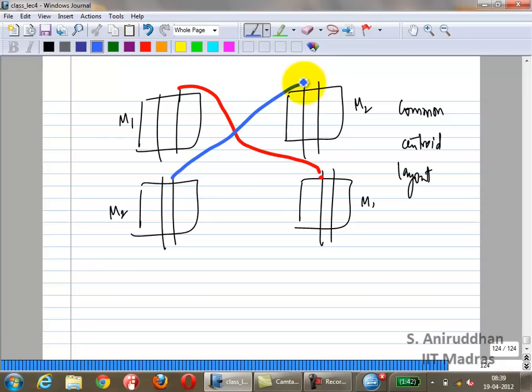So you will necessarily have to use different metal layers, so you may need to use M1 and M2 maybe, something like that, in which case the capacitance is slightly different, and quite possibly the resistance of the metal layers could be slightly different. Okay? So in this case, capacitance wise, it will not match, but basic DC mismatches, that is low frequency mismatches, would be much better.